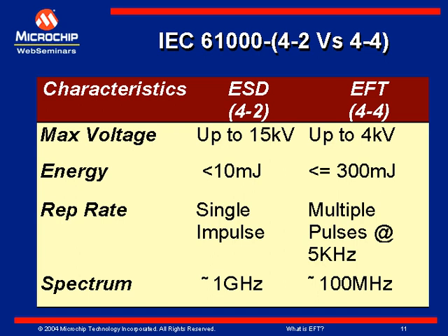In seminar 2, we looked at ESD, or electrostatic discharge. So now let us try to compare an electrostatic discharge event and EFT and how they stand against each other. First, if you look at the maximum voltage, in case of ESD, if you use an air discharge, the maximum voltage is 15 kilovolt for level 4, otherwise it's 8 kV. In case of electrical fast transients, it's just 4 kilovolts. Its peak amplitude is much lesser than ESD.